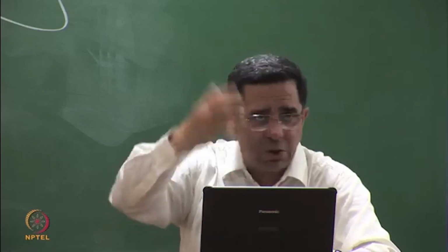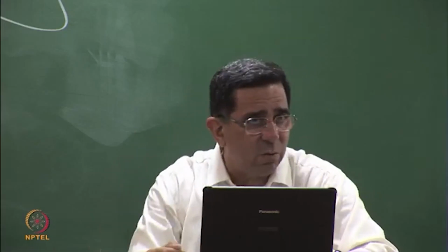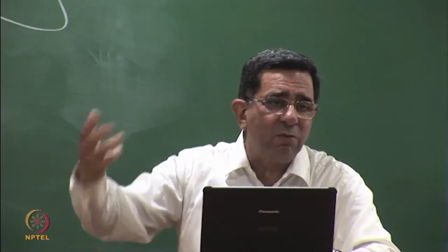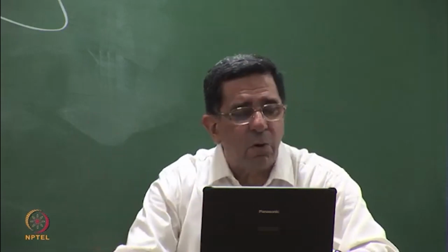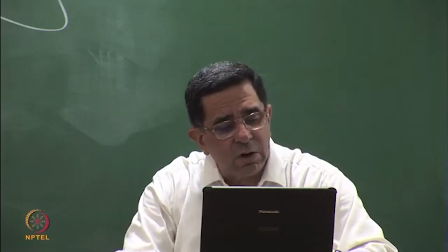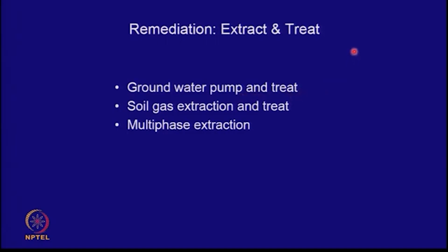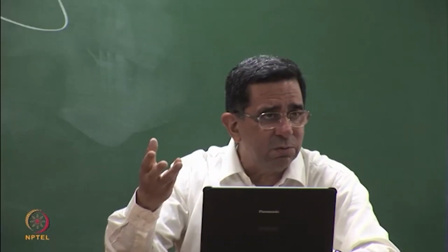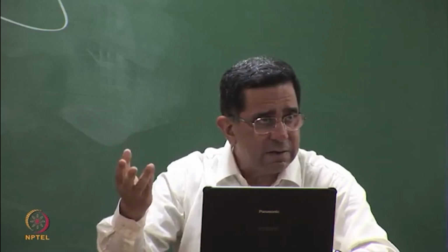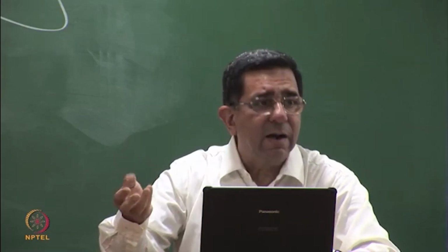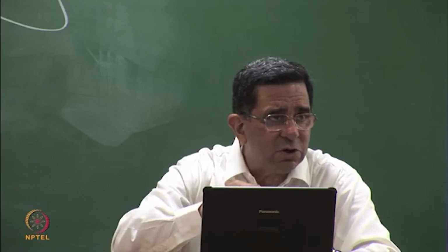The fresh water will wash the soil. It's like in situ soil washing. In the meantime, I'll treat this water and re-inject it. So you can continue to do the groundwater pump and treat till the water which you pump out is clean, which means that the contaminated groundwater has been removed, you have removed the contaminant, and the groundwater has come back to its original condition.